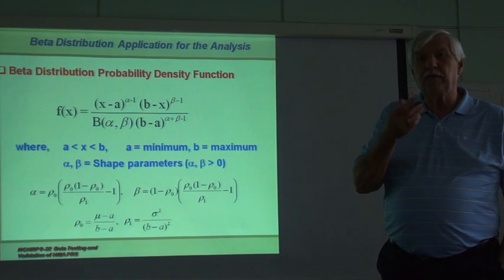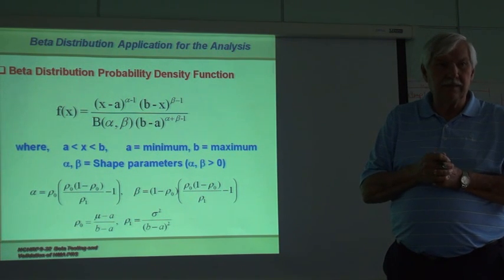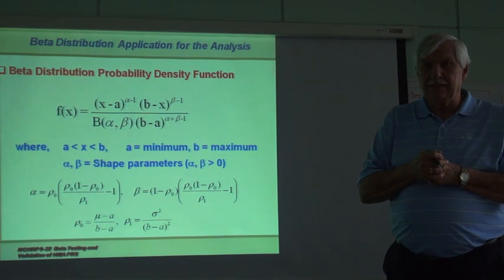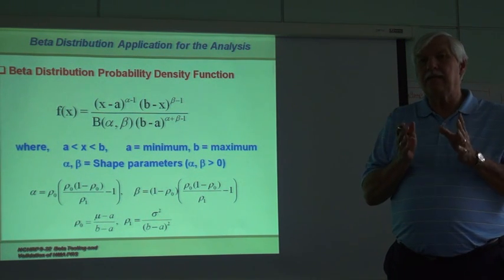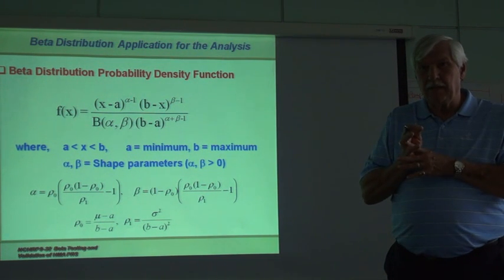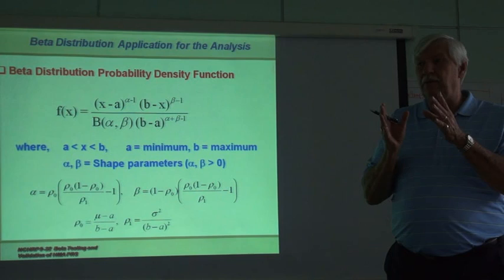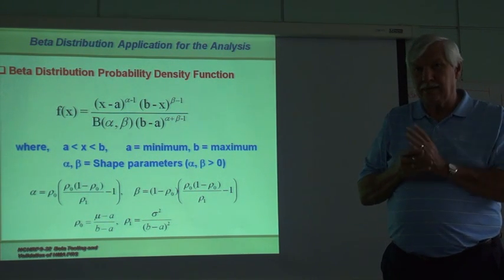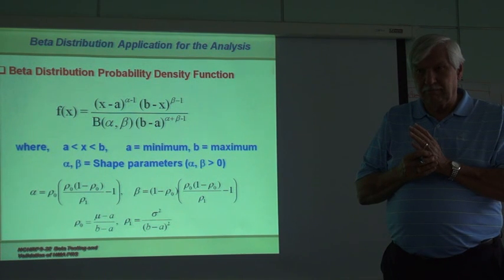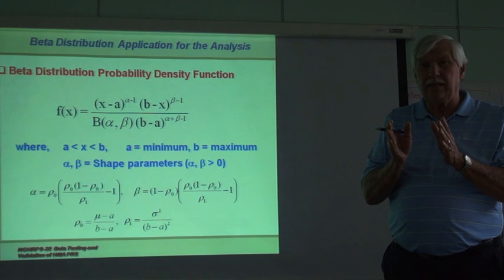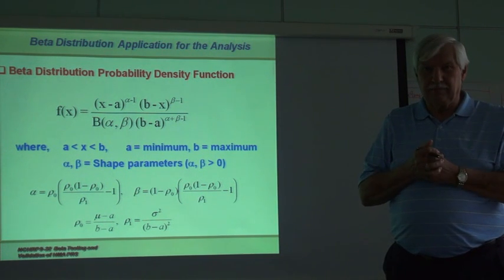If you know, for example, how we do distress in the MEPDG and the design guide, the percent crack frequency that I generate represents the amount of fatigue cracking I have in both wheel paths per mile.